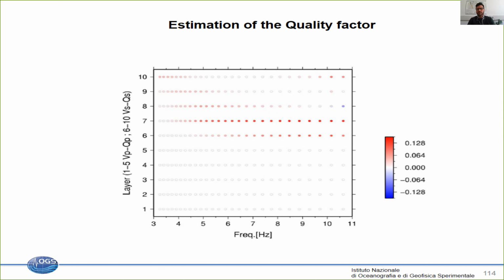in site response analysis. While for the shear wave velocity, that is the main parameter of our interest, at least for the use that we are aiming at in our field, we can nowadays obtain reasonable results that can then be used easily in numerical simulation, we cannot say the same for the damping or the quality factor.